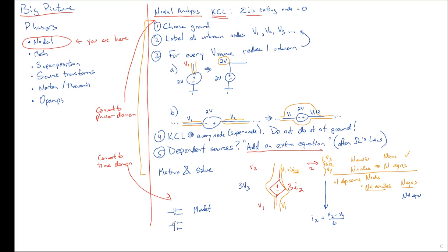When there's an electric field applied here, it allows current to flow through. It changes what this intermediate dielectric looks like and allows current to flow through here, whereas no current can ever flow in here. So when this is 0 volts, there's no electric field in here, and it looks like an open switch. But when there's 5 volts here, although still no current flows, it now looks like a closed switch between these two terminals.